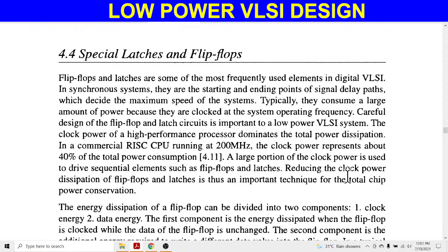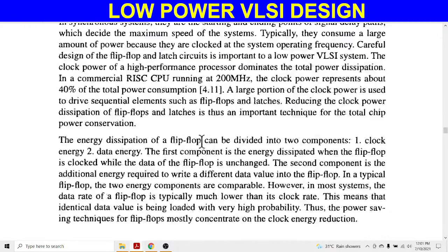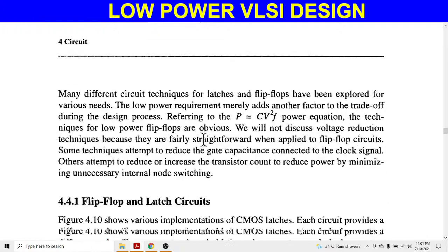Okay, this is power dissipated from any device, not just a flip-flop. So this power dissipation needs to be minimized. To minimize it, we know that the power is divided into these factors: capacitance, voltage, that is the swing voltage, or we can say the supply voltage, and the last one is the most important, that is frequency.